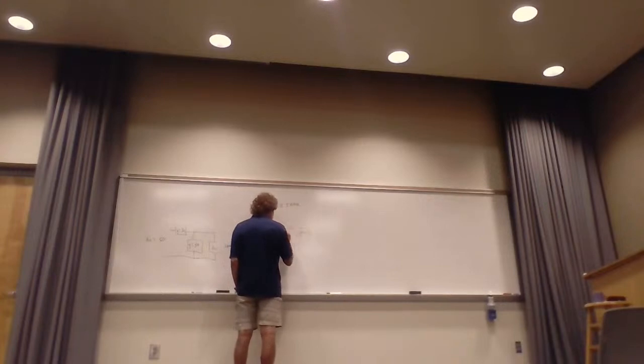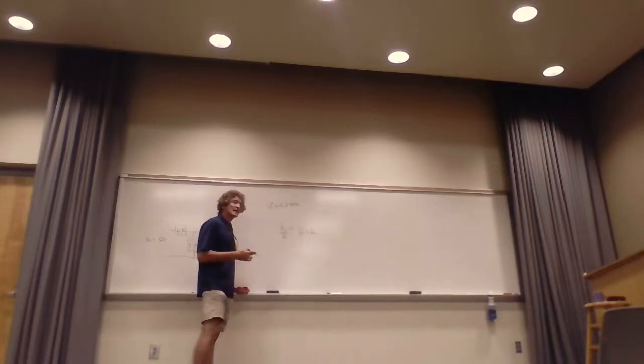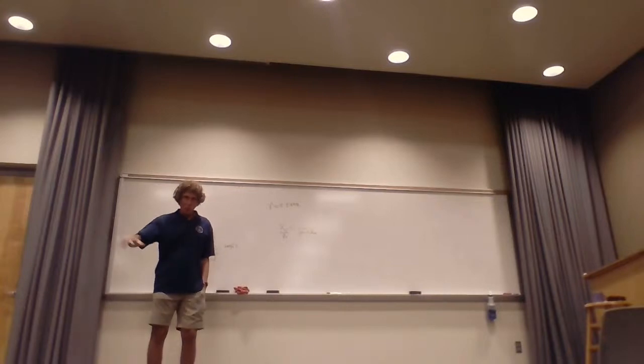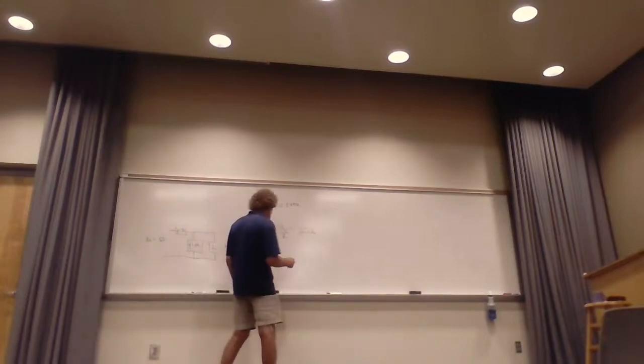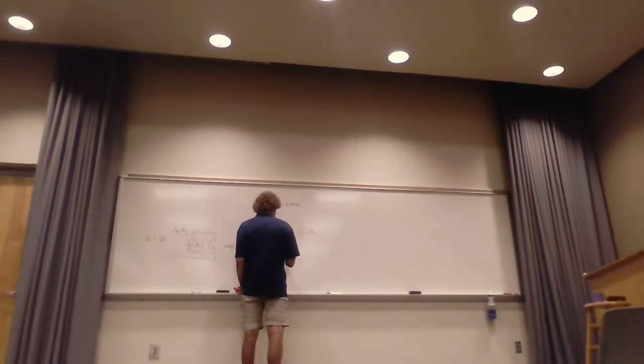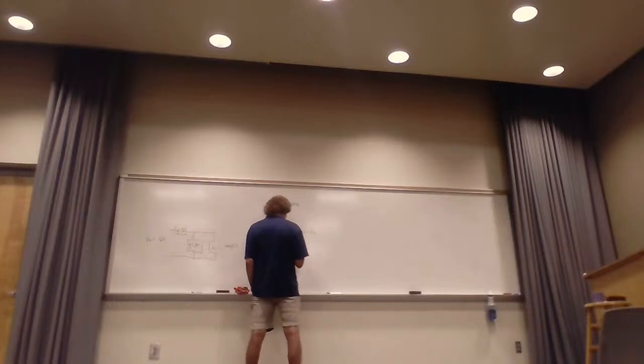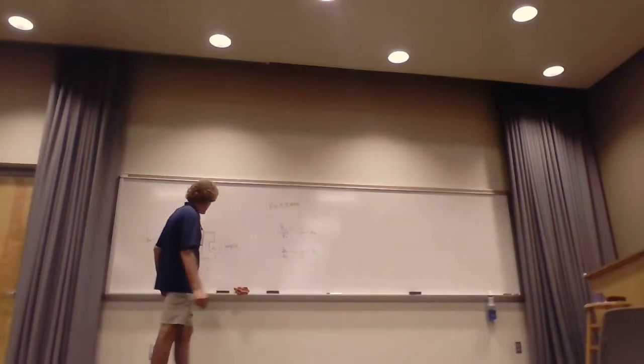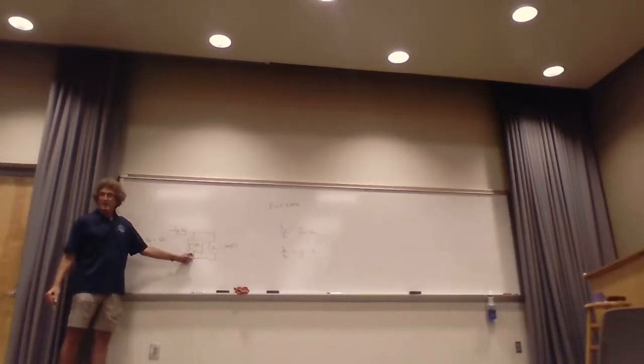So I divide this by Z naught. Now I have the normalized capacitive reactance, but I want the admittance, so I take 1 over that. So then I find the value of Y is going to be Z naught divided by XC, or it's simply equal to j omega C Z naught. And I set that equal to the value that I need here.